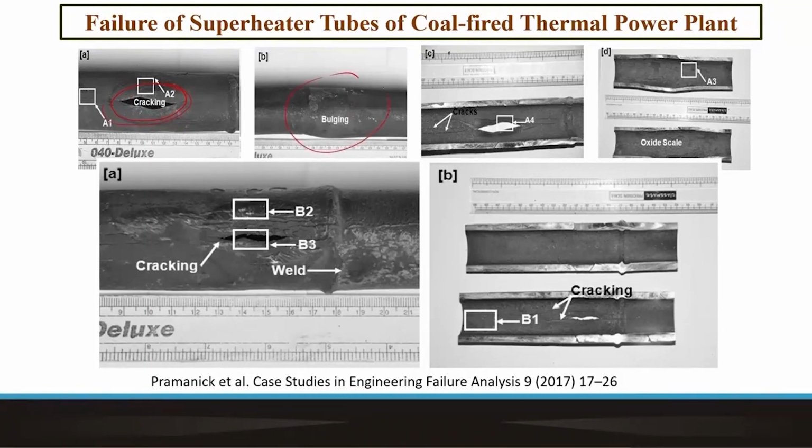So bulging is not so dangerous because this is just an indication that the failure might happen, and usually this kind of degradation initiates at the joints or at areas where, because of manufacturing defects or some other reasons, maybe bend regions and so on, the thickness of the shell is thinner.